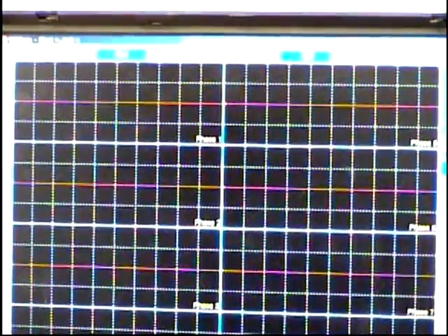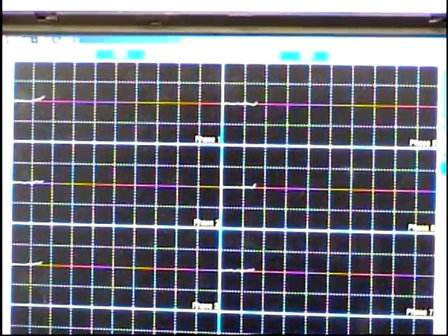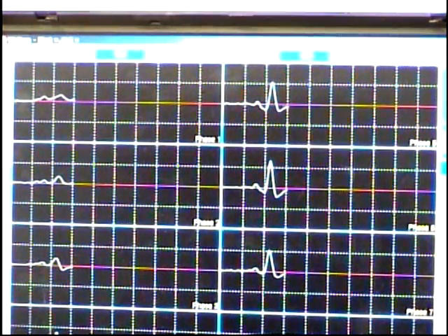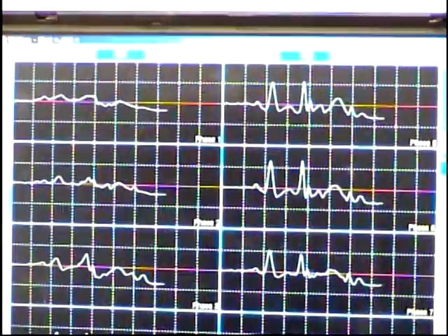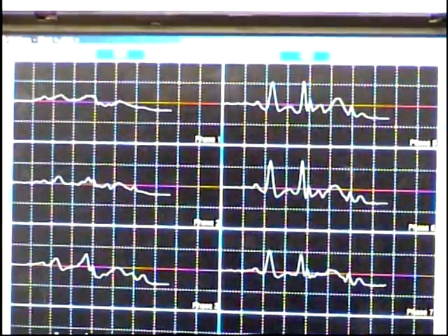When we hit the space bar, we start scanning along the length of the tube. You'll notice we're getting rises in our signal. These are all indications that there's a change in tube material. Notice I didn't say wall loss, and there's a reason for that. It's also what's called hydrogen damage. A lot of times with hydrogen damage, you'll get a rise in signal like this. Now if you go to UT that, it's going to show almost near full wall. So say if this is 250, it may show like 240 or 248. But you're looking at the back wall reflection, and if there isn't any, that shows you that there's what's called hydrogen damage in the tube.